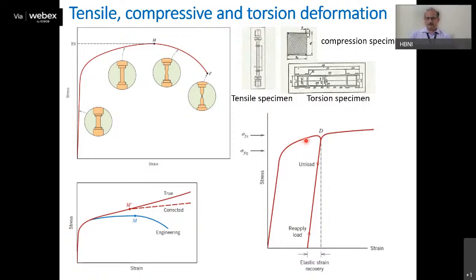So when you release stress from a certain stress condition and you unload it, there is some remnant, that is a plastic strain. This is still there, and whatever the elastic strain was there, that is recovered when you release the stresses. But when you increase or reload the sample from this stress state, then it reaches a yield strength which is higher than the yield strength of the initial sample. So this is a kind of strain hardening that happens in compressive stress. Okay.